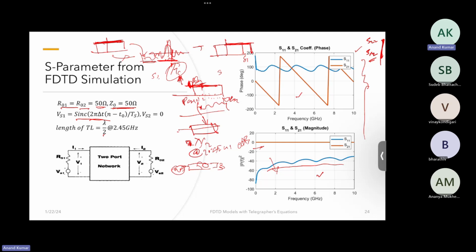Yes. The first thing you emphasized was, and I forgot to emphasize, that we don't have to do a frequency sweep, so we just send in one pulse and we can get the entire S parameters. Regarding the group delay and similar quantities, you can do it in post processing.